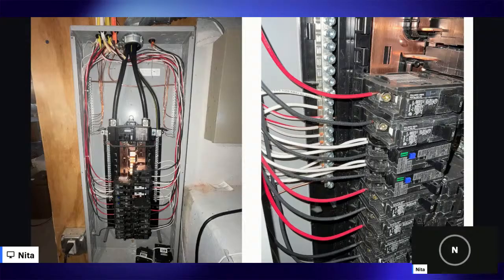Service drop conductors. My service drop conductors connect with my service entrance conductors at the service point, which is a splice, which is a designation of responsibility. After the service point, the homeowner is responsible for the equipment. My service entrance conductors will enter the gooseneck, the service head. Before doing so, I want to see a drip loop.